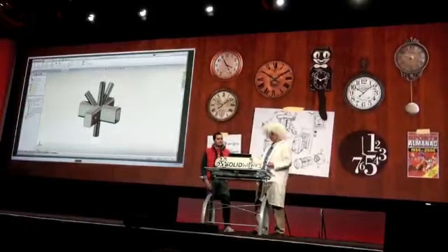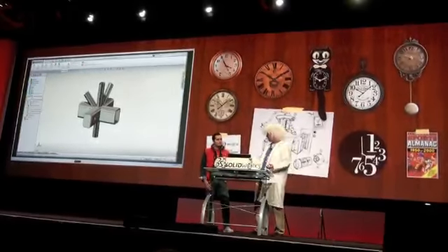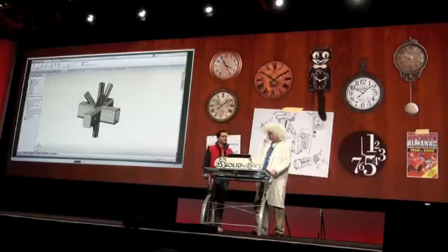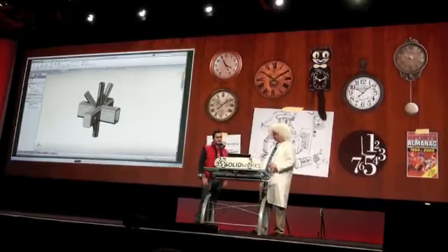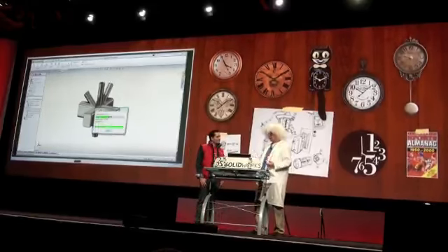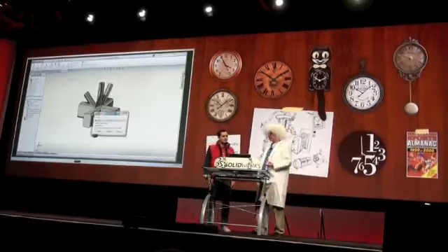You can even add additional features or parts to the sub-model to easily evaluate different local design concepts. Hang on. What happens if this design changes, you know, the full model? Well, that's not a problem. This sub-model is parametric. So when you modify and rerun the full model, those loads and boundary conditions will update on the sub-model as well.